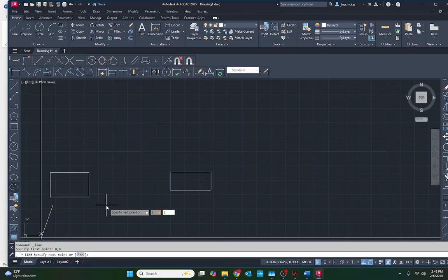So when I hit enter, the line is placed, and then you can see how we're set up to continue a line from this point. Now if I do this again, I'll type 2, 2. You see that again we move up, and now this point happens to be 4, 4.